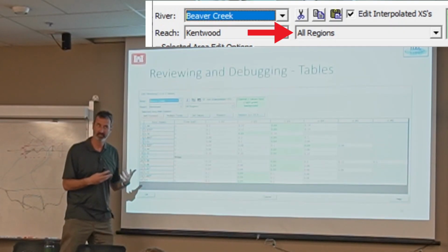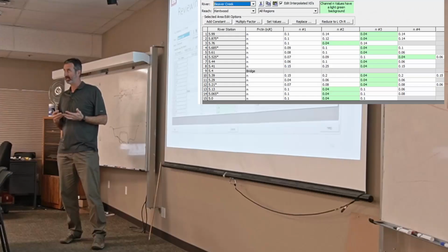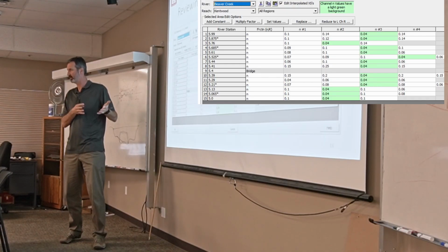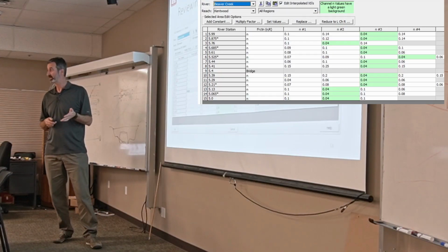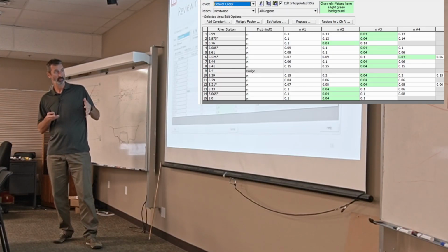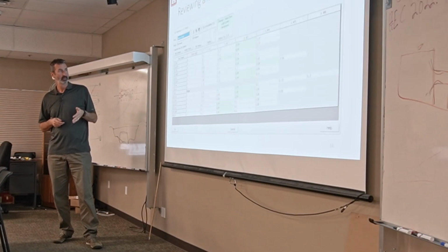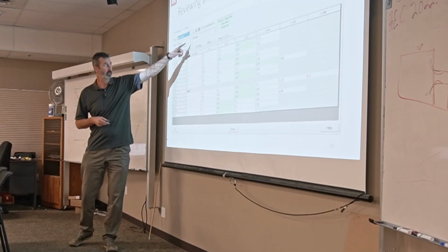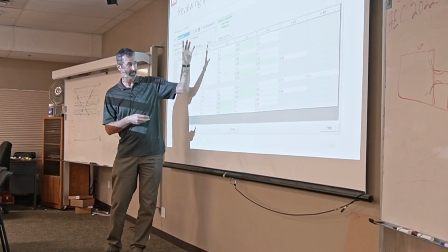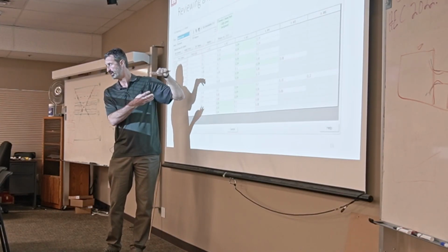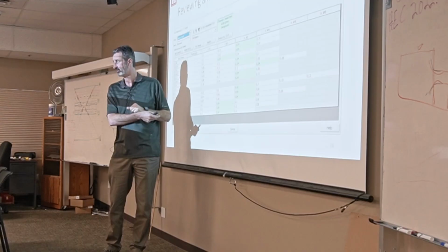If the procedure for calibration, a good procedure is to start off with just trying to calibrate the stuff in the channel first. Because if you don't get the channel right, it's really hard to get the later ones right. So just start off with getting the channel calibration. So you're using one of your lower flow events or lower flow profiles, and then turn this category on to just channel, and then go do some blanket the whole thing, raise them up, or just a strategic part of the table, raise them up in n fractions.